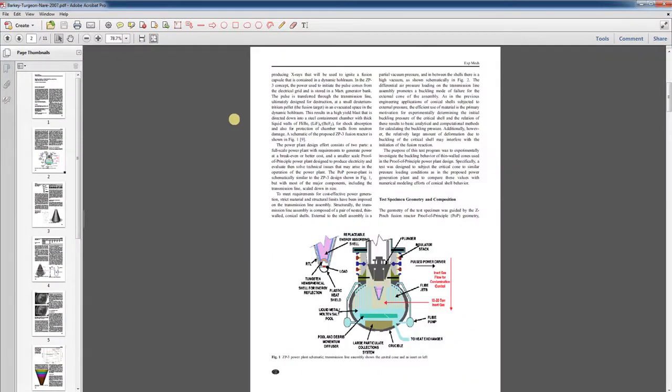Well, in the course of this, they wanted to know what the buckling pressure of these cones would be, and how close their analytical and finite element methods would be for this. Buckling problems are very imperfection sensitive. And if they could integrate any stiffeners in the design of these cones, then maybe they could increase that buckling pressure. So, if you pull a hard vacuum, you're around 14.7 or so psi of differential pressure, depending on what's going on the other side of that if you're exposed to atmosphere on one side. So it could be as high as that.